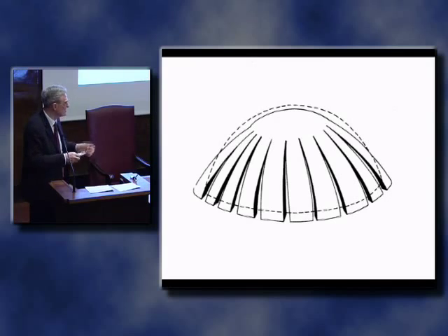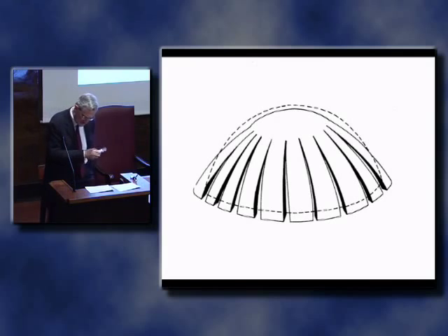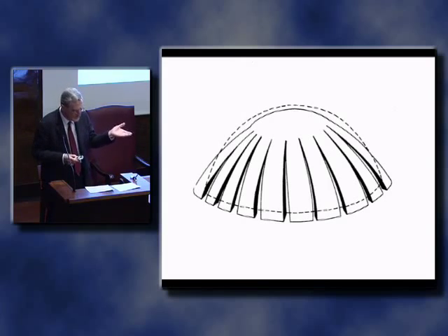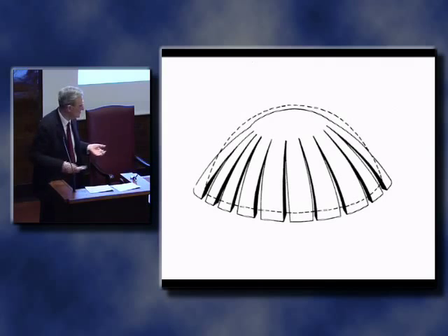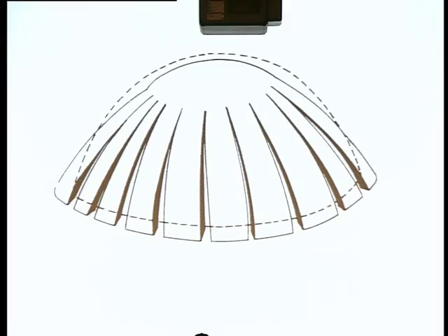The dome must inevitably crack, and as I say, shown grossly here are cracks which would allow the dome to move outwards in diameter. It's important to realize that this cracking, just as for the arch, is caused by movement and not by stress. We saw those tensile stresses on the previous slide near the base of the dome. But as long as the dome does not increase in diameter, there is no possibility of cracking due to stress. It is the movement which causes this. The stresses can be quite low, but nevertheless, this cracking will occur.